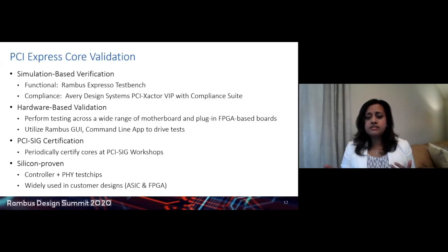It goes through hardware-based validation, where we perform testing across a wide variety of motherboard and plug-in FPGA cards. It goes through PCI SIG certification, where we have periodically taken our core for PCI SIG certification at the PCI SIG workshops. And it is fully silicon proven, where we offer controller plus PHY test chips. In addition to that, it's also widely used in a large number of customer designs for both ASICs and FPGAs.